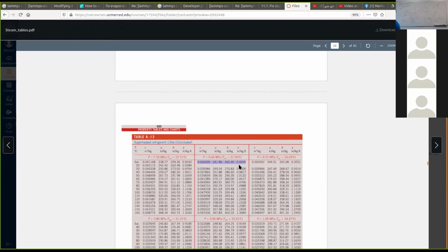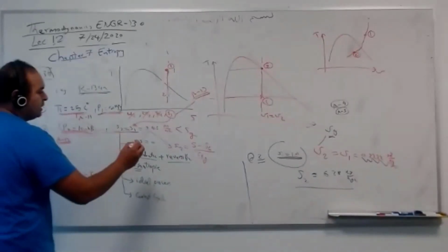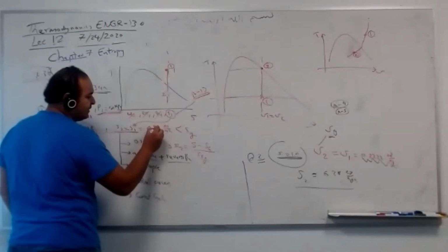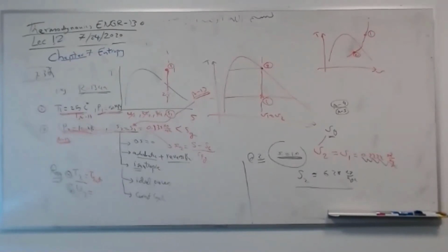Once you get S1, it's most probably in between, something like 0.93, about 0.93 on average by your eyes. 0.922, 0.952, it's about 0.935 or something, somehow average. So you almost have S2. It means that you have S2, 0.935 for example. Go now to state 2. You have P2 equal 100 kilopascal. Pressure means go to the table A.